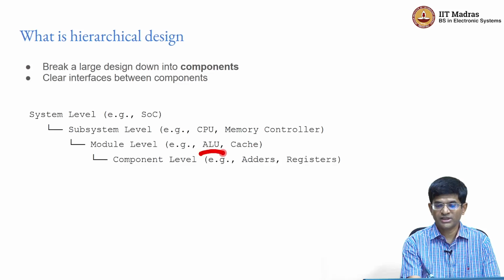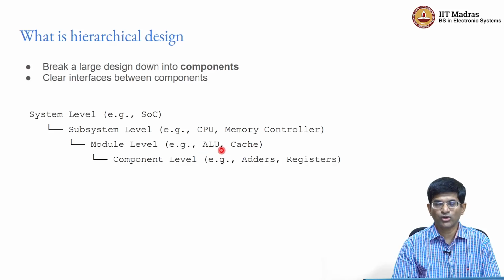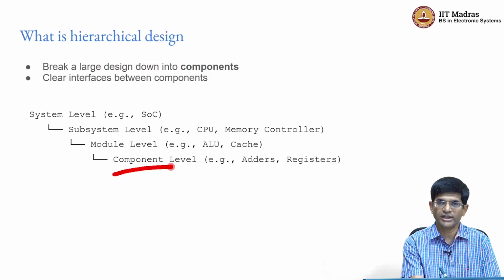But going even further down, you might find that inside the ALU you need to perform addition operations. Inside the register file you need to have optimized registers which have very fast read response times. The TCQ, the clock to output delay of the register, should be very low, right? Similarly, the setup times and so on should be well optimized. So in those cases, what you would very likely find is that these are now at a small enough level that individual designers could probably be handed over a particular task and told, okay, this is a component that you need to design.